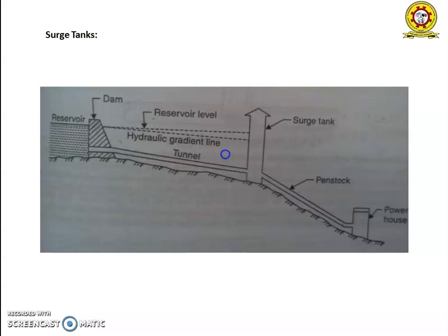The change in pressure, rapidly above or below the normal pressure, causes sudden changes in the rate of water flow from the pipe according to the demand of the prime mover of the penstock. It serves to supply water to the turbine in case of increasing load conditions, and as a storage tank in case of decreasing load. So this is the surge tank.